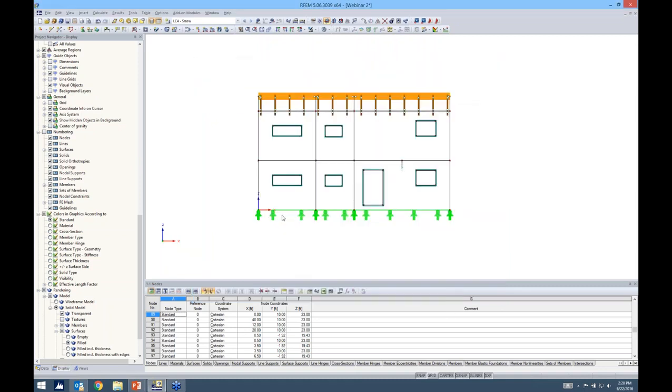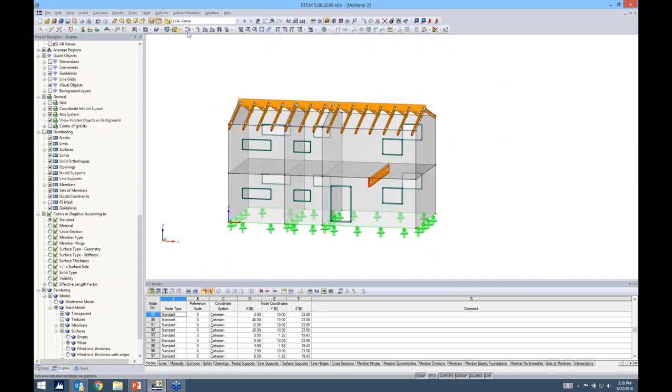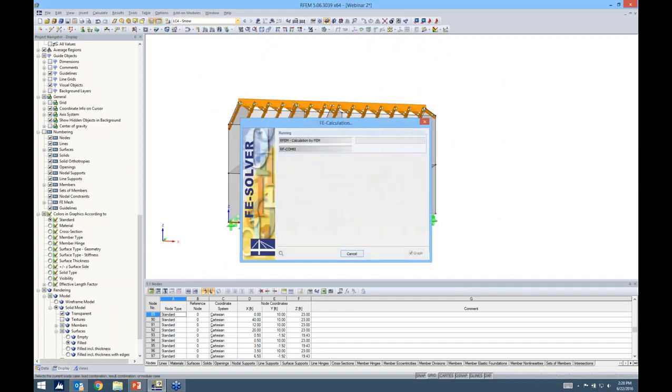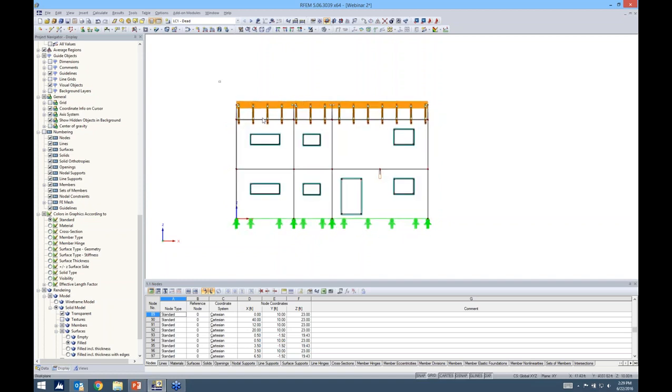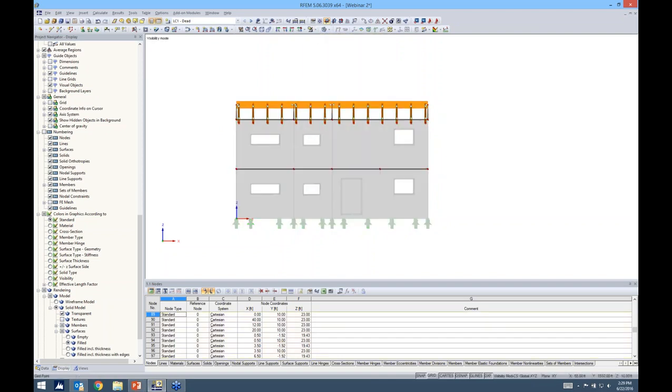Okay, so I can click OK out of here, and you'll notice that when I'm looking at my drop-down box now, which previously was empty, I now have all of my load cases, and the program automatically created all of my load combinations according to ASD and LRFD. Now, when you're applying loads, you want to make sure that this is set on the correct load case that you want the loads applied to. So I think what's easiest here is to highlight our floors and make this visibility based on the selected objects.